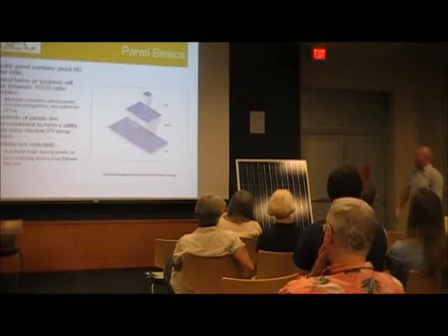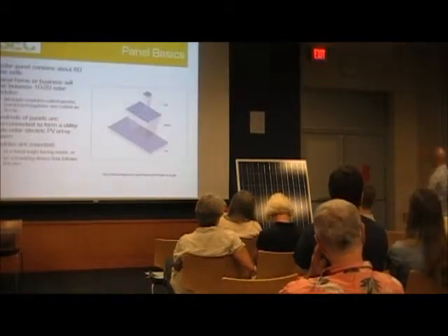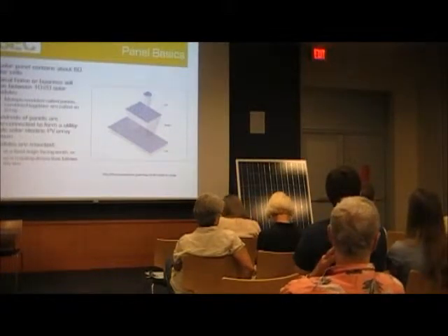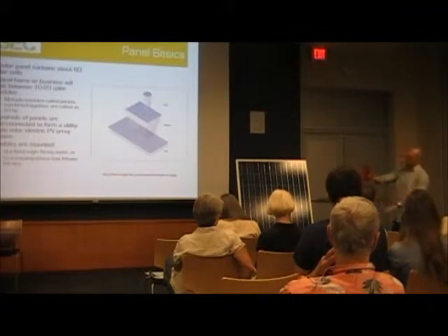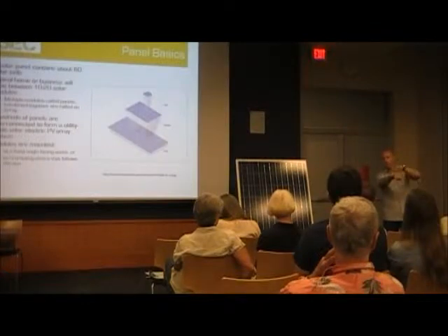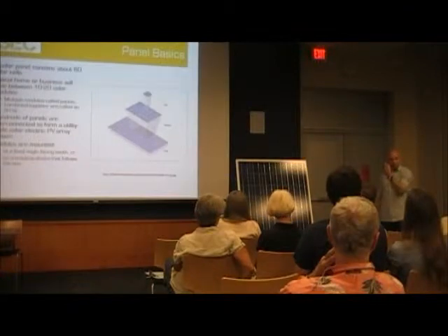But they have an interesting cylinder, and when the sun moves, like eventually when I come up on the east here, as I start rolling, the production pops up because the sun's moving and it gets more intense. Cylindra was a cylinder, so their whole idea was, no matter where the sun's up over here, I'm always hitting the same amount of silicon all the time. And they have little spaces between them, and you paint the roof white, so you get deflection, you get ambient light underneath. So they were saying they were always on. But they didn't produce as much power.